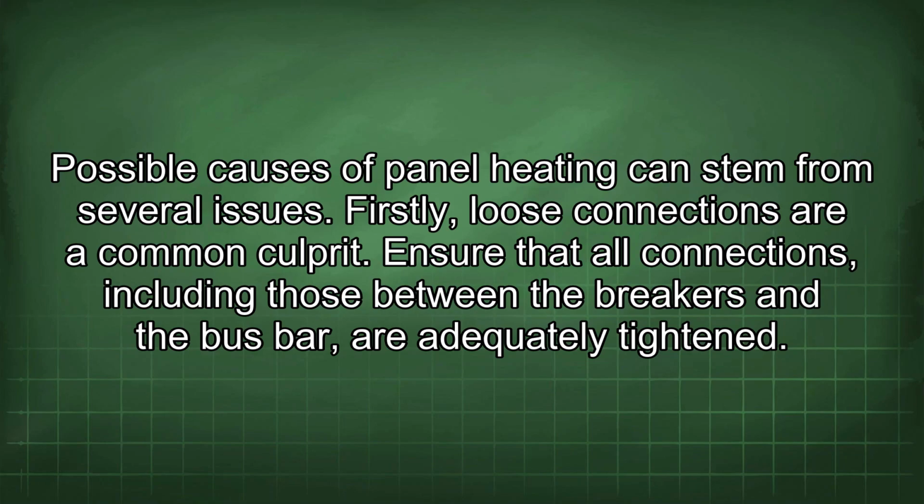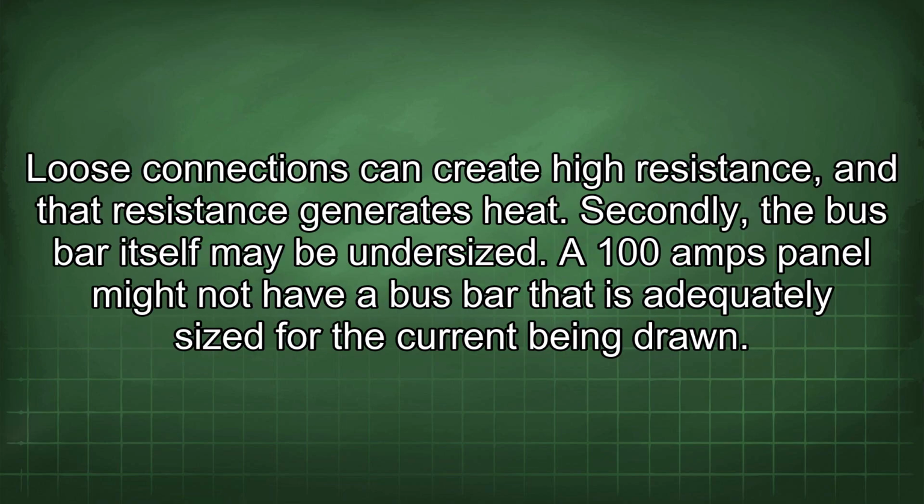Possible causes of panel heating can stem from several issues. Firstly, loose connections are a common culprit. Ensure that all connections, including those between the breakers and the bus bar, are adequately tightened. Loose connections can create high resistance, and that resistance generates heat.